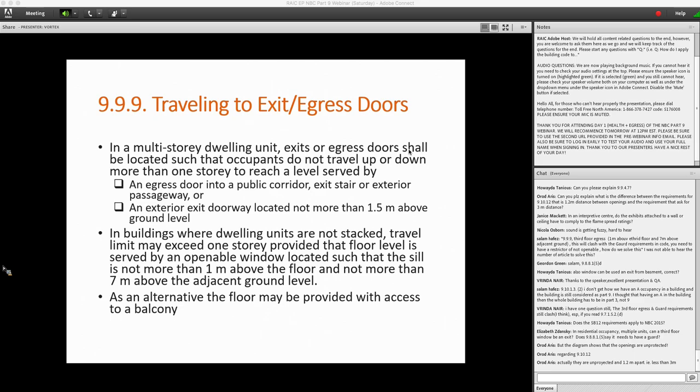So if the A is a minor occupancy, not a major occupancy, where it's not a principal use of the building and doesn't occupy more than 10% of the floor area in the building, then the A occupancy can be classified as a minor occupancy, in which case the entire building can be designed to Part 9. If it becomes a major occupancy, then you would have to go to Part 3 of the building code.